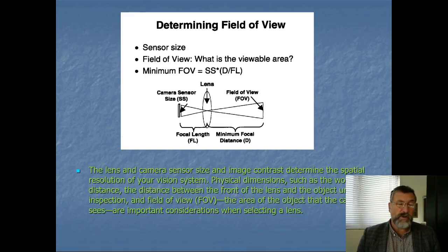For example, you have to get the right kind of lens for a given size of sensor, because if you had a very large sensor and a small lens mount, you would get vignetting and you wouldn't get a good effect. So you have to have it all matched. Or if you've got a very, very high resolution sensor, then you need a megapixel lens to go with it. Otherwise, you'd be wasting your money on an expensive sensor with a poor quality lens. So it's good to get them matched, really.